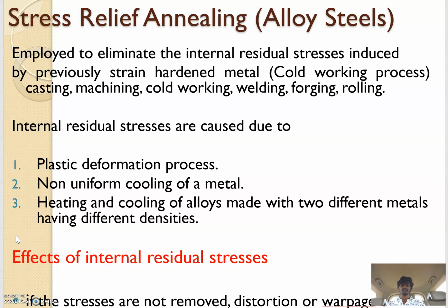Internal residual stresses are caused due to plastic deformation processes, non-uniform cooling of a metal, heating and cooling of alloys made with two different metals having different densities. The effects of internal residual stresses are: if the stresses are not removed, distortion or warpage of material occurs.